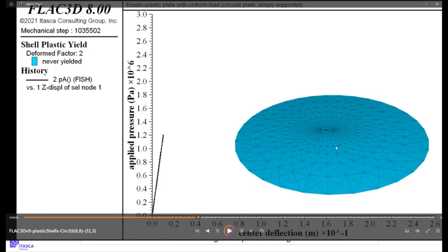And so what should happen here, since it's being pressure loaded, the highest stress on this is in the center here. And so that would be the region that should begin to fail plastically. And as it fails plastically, because it's bending, you have compression on the top and tension on the bottom. It starts to yield. It reaches the critical point on the outside, top and bottom, but it still has capacity inside. But if you continue to bend it slowly, the yield zone grows till it gets all the way through the whole entire shell structure. And after that, it can't carry anything anymore.